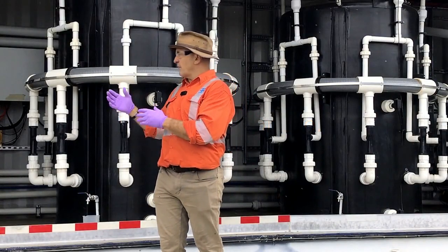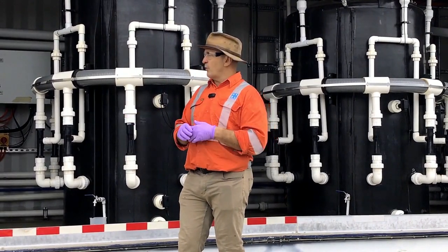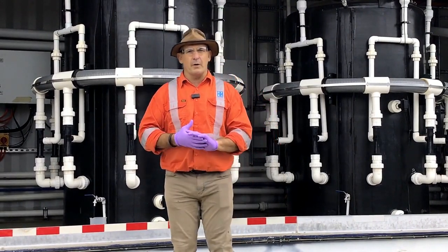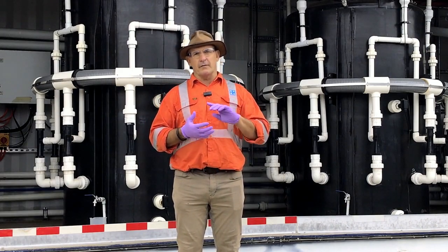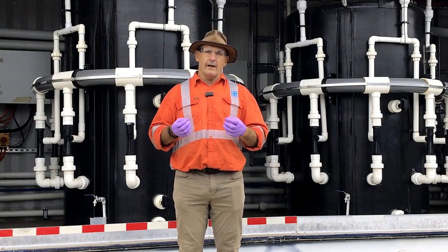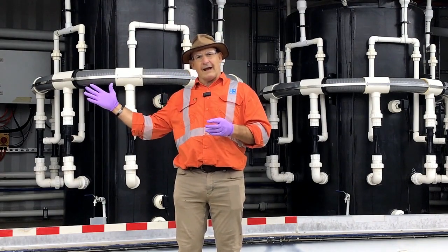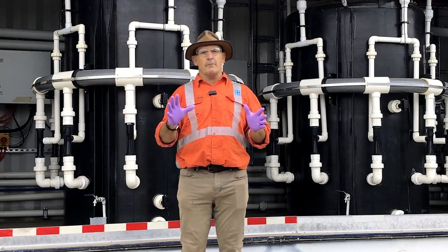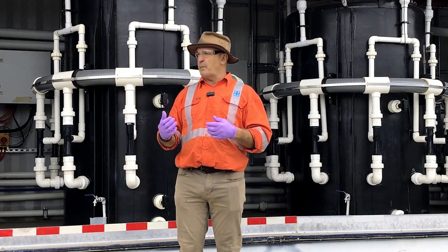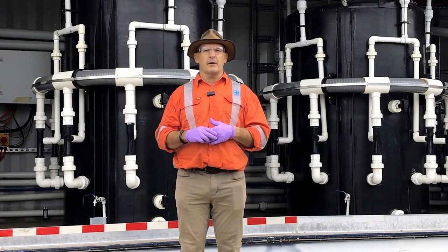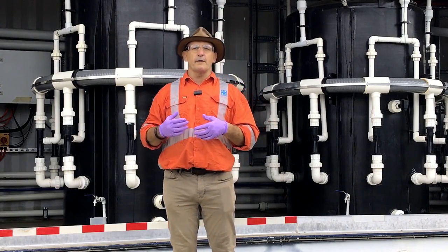This first stage in these large vessels, we call that primary fractionation. It's fairly straightforward. You guys will have seen, no doubt in your experience, DAF plants. You'll have seen sparging plants in sewage treatment. You'll have seen lots of ways where water and air are mixed and you'll get a foam at the top. What we're doing is we're just taking a cut of that foam using a simple spillover weir approach, and it just helps us to elevate our PFAS levels from a baseline of about 1 part per billion in the groundwater, gets us up to 5 to 10 parts per billion, so we just get a healthier foam.